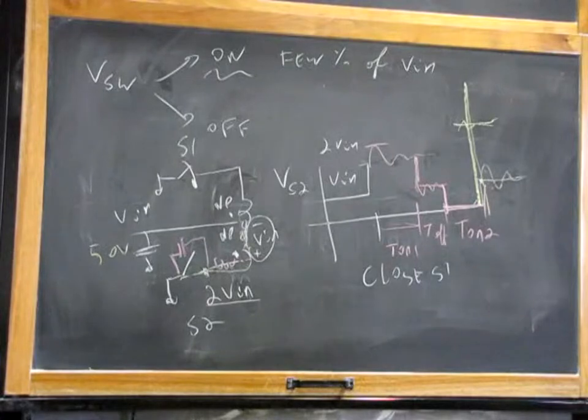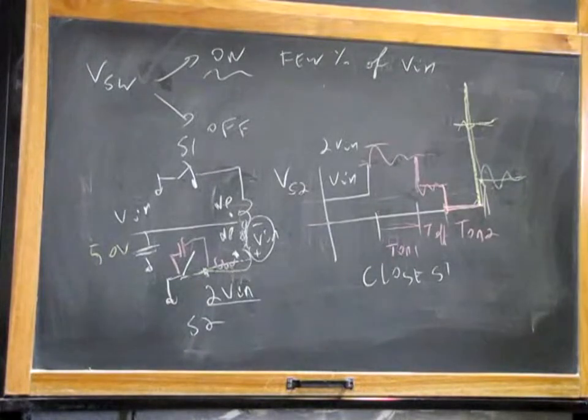Not only that, but if you go above the absolute maximum rating of a component, even if it survives, it could get crippled. So its reliability goes down, the electrical performances can go down, and so on. Okay? That's good.